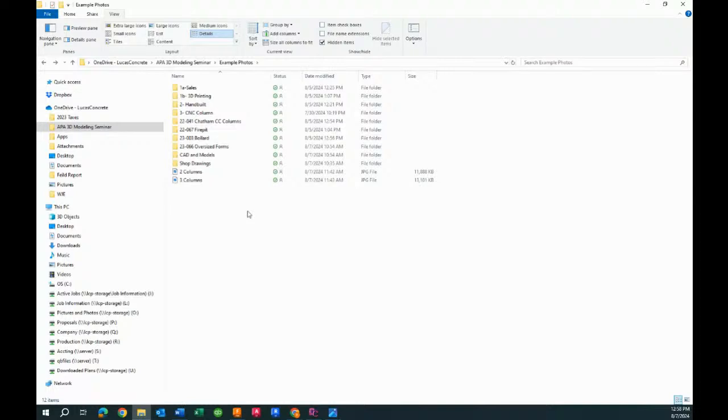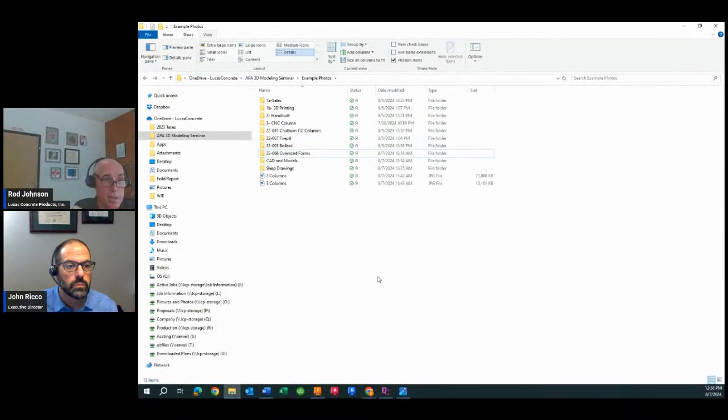The only issue you have is when you sharpen bits. If you send off your bits from your CNC to be sharpened, that tends to make your tolerance of putting those things together a little bit tighter. So you just got to make sure you compensate for that, add an extra couple thousandths of an inch width-wise. So instead of saying this is 0.75 inches wide, you might say it's 0.78, or 0.77 inches. But that's the only other issue we've ever really had, if we've made it to where the tolerance is a little bit too tight.